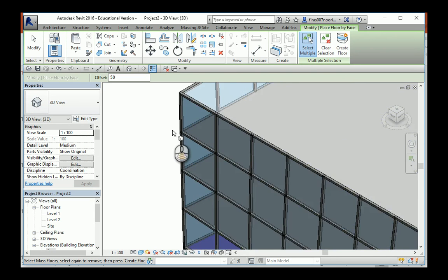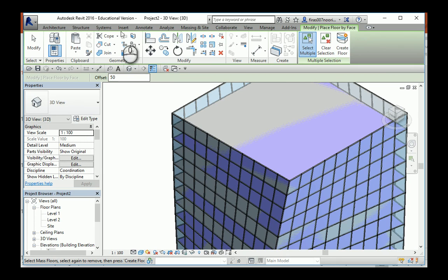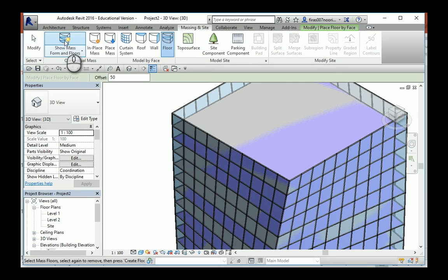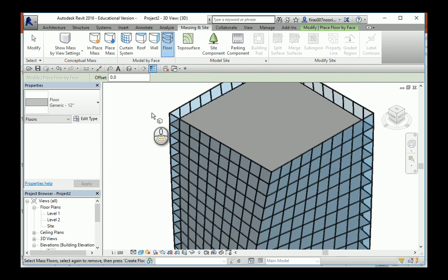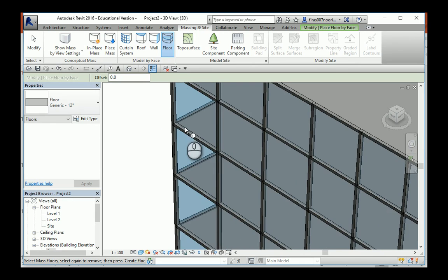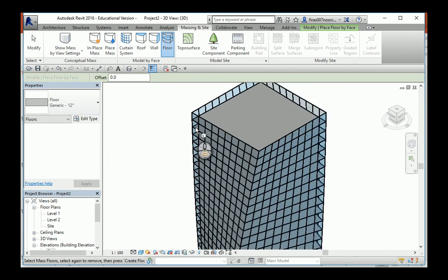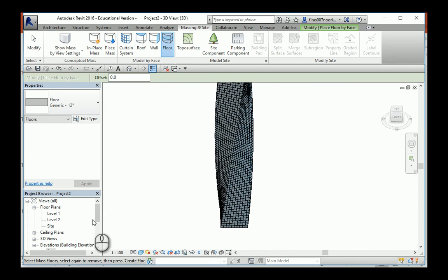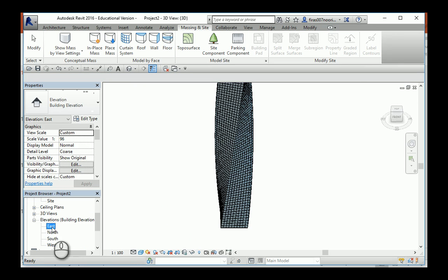See, lovely, huh? If you go to View, you can turn off the whole thing now, sorry, to Massing, and turn off the form that you just imported from the conceptual mass, and you get real slabs, real mullions, real glass wrapping around that nice shape for the Cyan Tower.